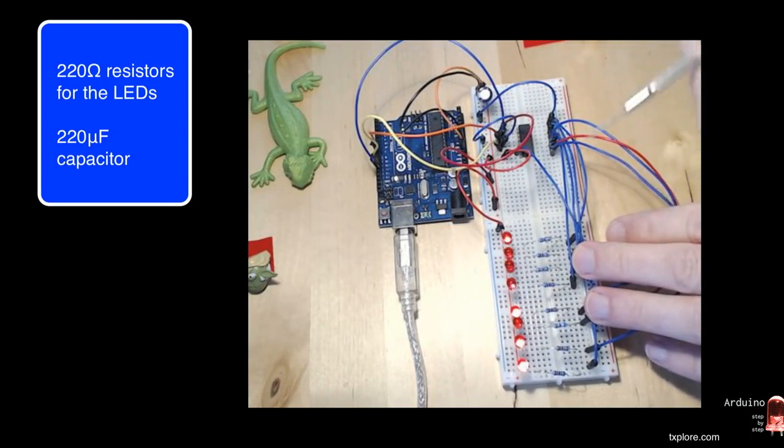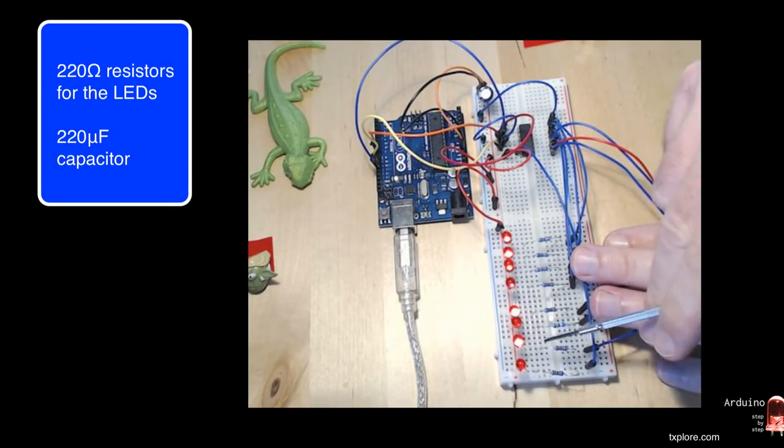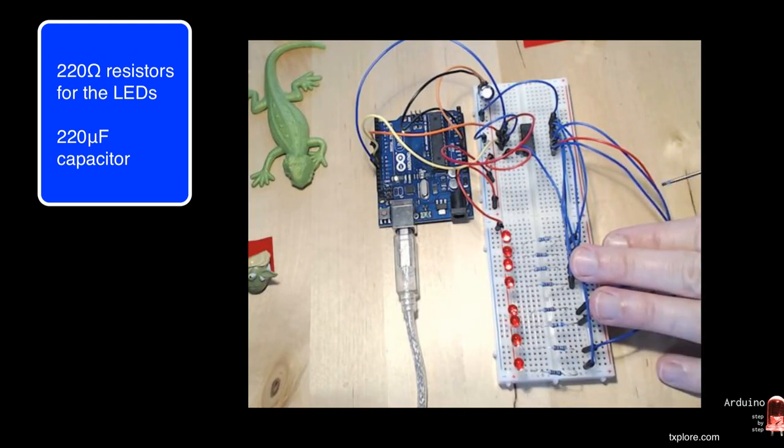Now, before I connect any wires, I move on to plugging the rest of the components onto the breadboards. So I've got approximately 220 ohm resistors protecting the LEDs. I just plug one leg of the LED, the positive leg, directly onto the positive rail, so that saves me a few jumper wires.